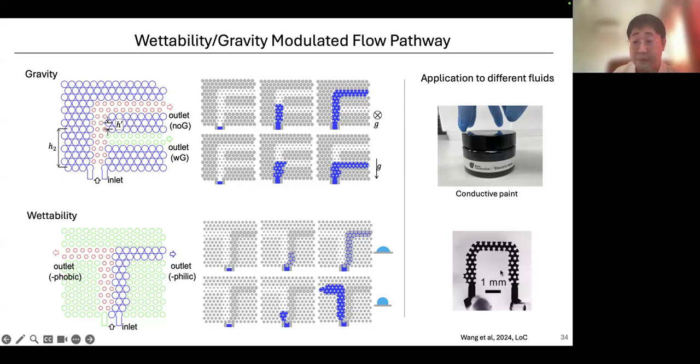But in this particular experiment, we really need to slow down the injection speed because from the analysis, again, the key is to make sure the capillary forces are much larger than the viscous pressure drop. Because we have much more viscous fluids, we need to reduce the injection speed. Although the scale is pretty small, this experiment took approximately 1 hour to complete.